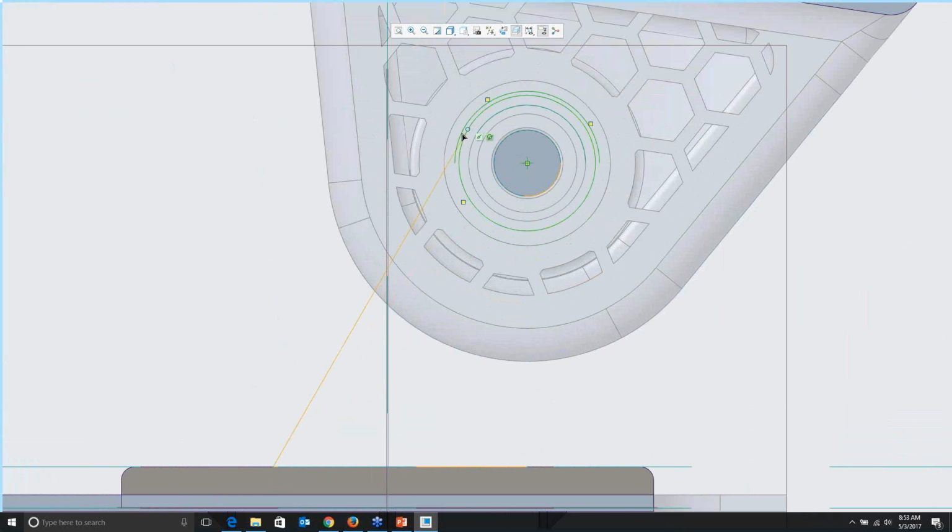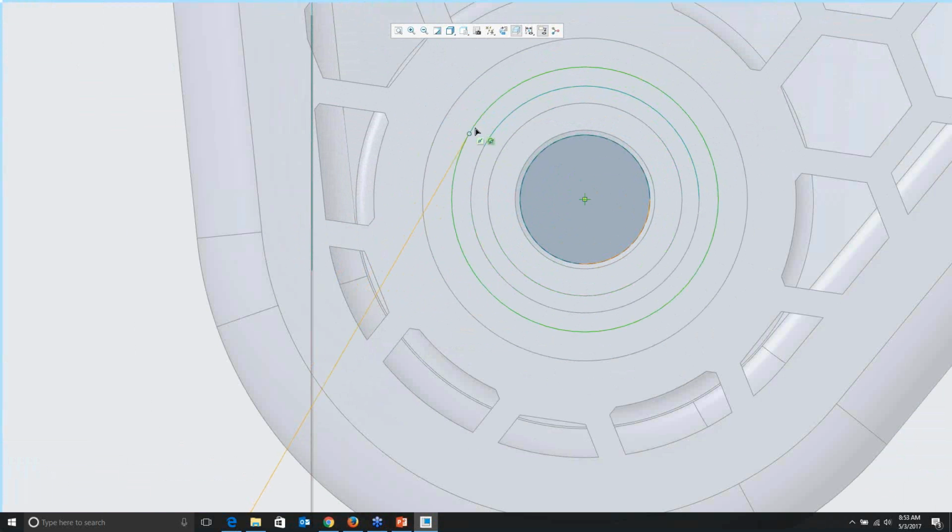Yep, and then I'll go ahead and finish that off with a tangent constraint over here. And once again, you'll notice right here as I have my mouse on that circle, I want the line to be on the circle and tangent to it. And those are the two constraints that pop up just in that green highlighted box, right?